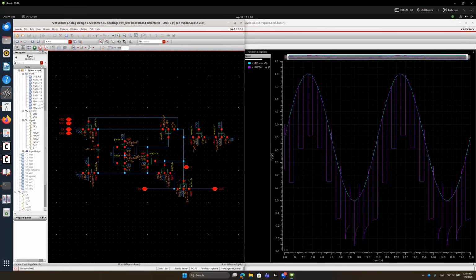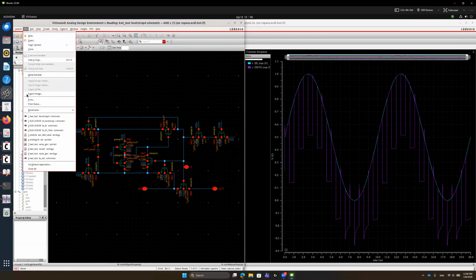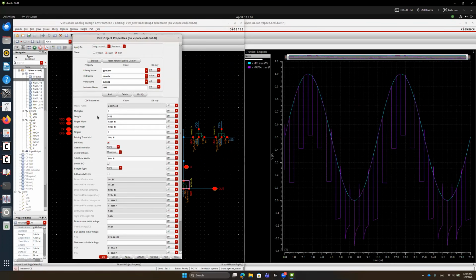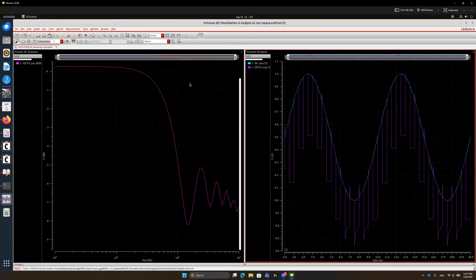So we should not increase this parasitic cap too much when designing each transistor. So let me make it back to 45 nanometer. Yeah, so because of this action, probably this peak-to-peak voltage here is increased from here to here. But I believe this kind of phenomenon is included as a gain increase, but it's not our intention. It is not as we designed, which is not good.